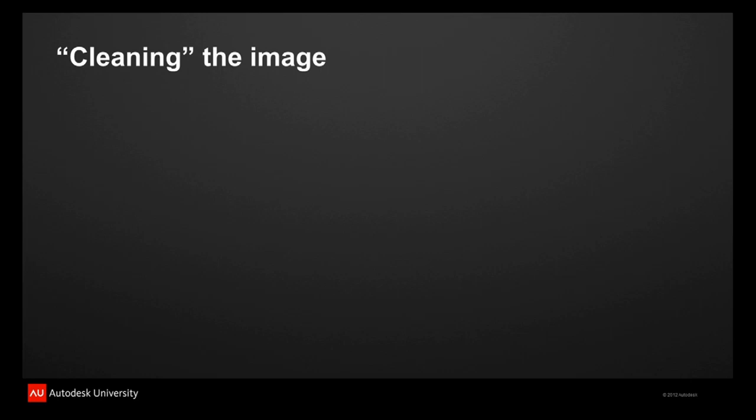Let's say you've got a piece of paper that's 20 years old and it's a bit rumpled and it's had a couple of coffee stains, etc. Then when you're scanning this image, you might find that you've got different scales along this image. So you can't just use a standard, specific scale to be able to rectify that. We call that rubber sheeting, by the way. But these are the tools we are going to use to try and get this image as close to perfect as possible before we start vectorizing it. So the first phase, I call cleaning the image, and that's removing speckles and things like that.